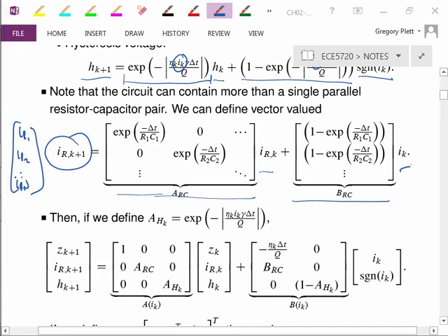The trade-off is the more of these I have, the better it's possible to simulate battery behavior, but it's also more difficult to come up with system identification of the RC factors. And it also makes the simulation slower because there are more equations in the simulation.